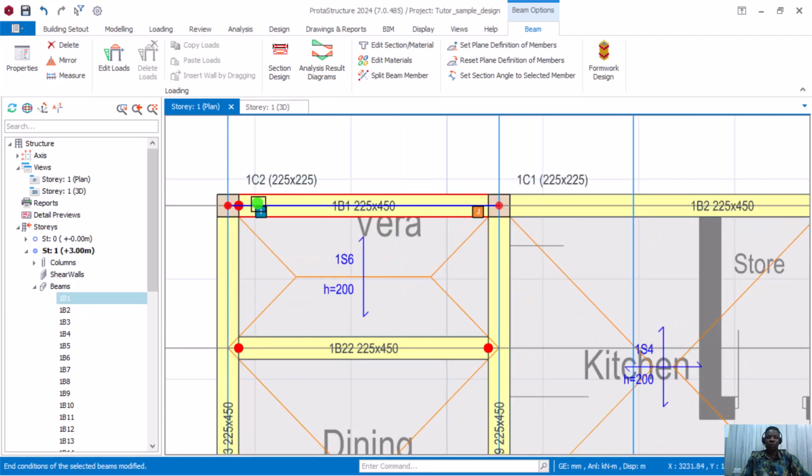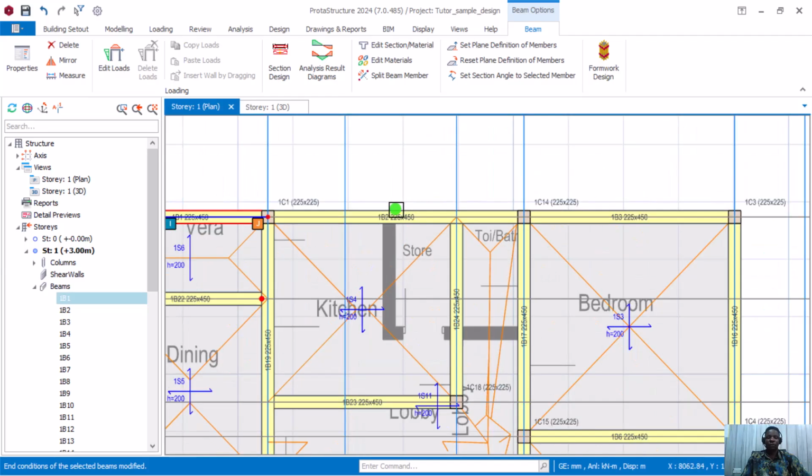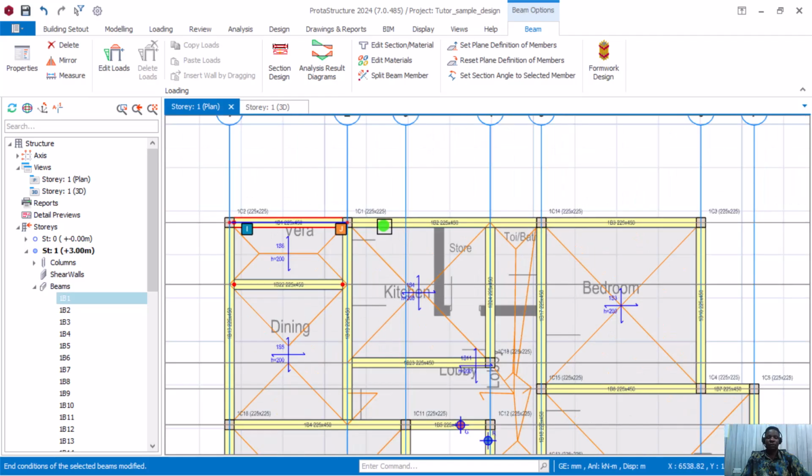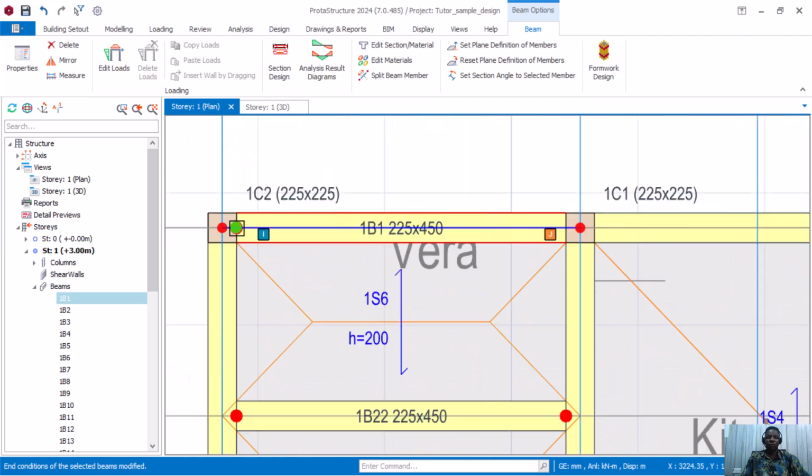So you can see in this condition, because we say I, it's going to hinge only the I direction. It's not going to hinge both. Okay. So if you've made a mistake and you hinged numerous beams, you can just click on the beam and hinge one connection. Like in this now, if I hinge this, if I want to hinge this other one now, there's no way I'm going to hinge this and hinge this.